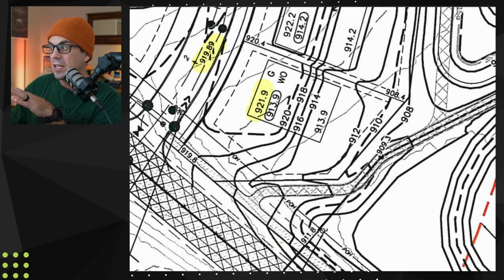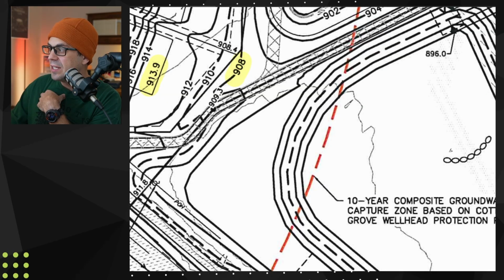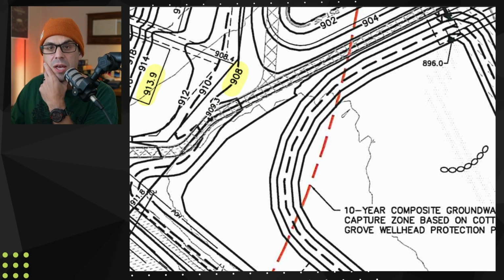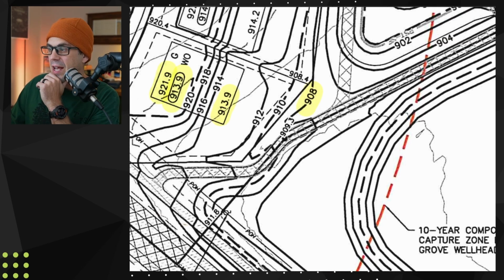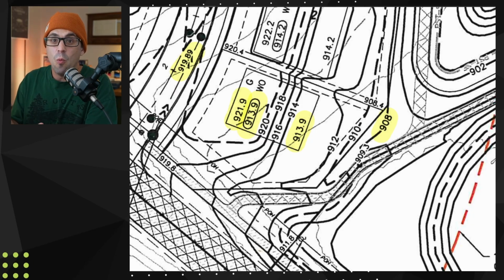So this designer wants this driveway essentially flat, but we have a walkout elevation, 913.9. So as the grade profile is dropping here, 913.9, and then your grade will drop continually till you get to this basin. And that's designed to hold or trap water until it goes away. So this is very important, especially if your city or county is going to hold you to this. You're definitely going to want to know what they're holding you to. So make sure and check your grading plan.